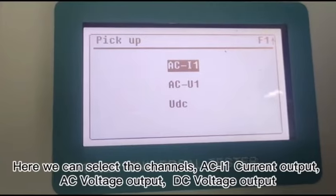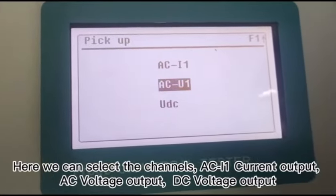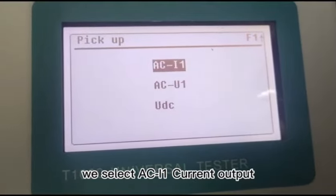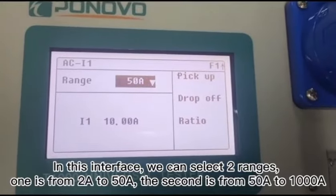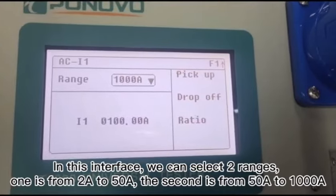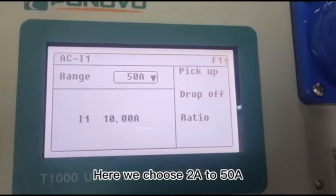Here we can select the channels: ACI1 current output, AC voltage output, DC voltage output. We select ACI1 current output. In this interface, we can select two ranges, one is from 2 amperes to 50 amperes, the second is from 50 amperes to 1000 amperes. Here we choose 2 amperes to 50 amperes.